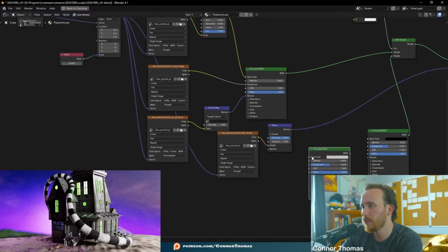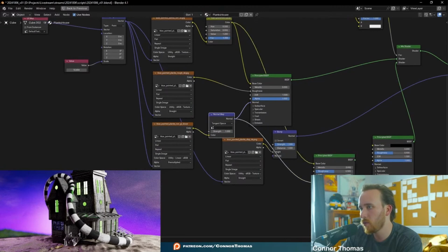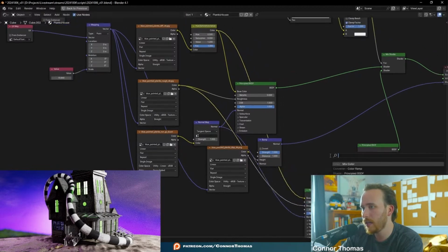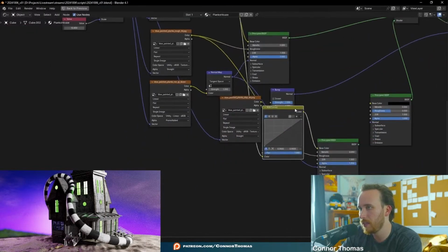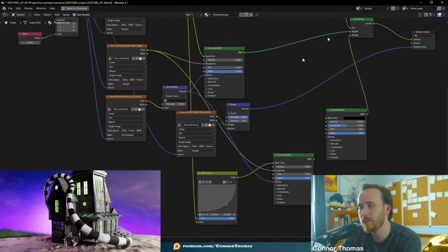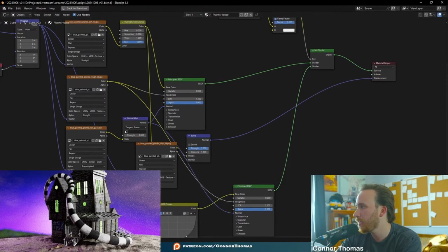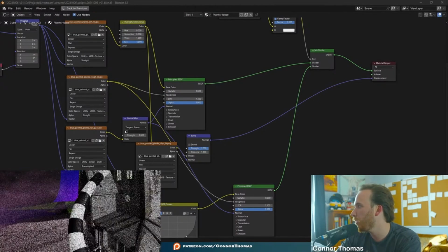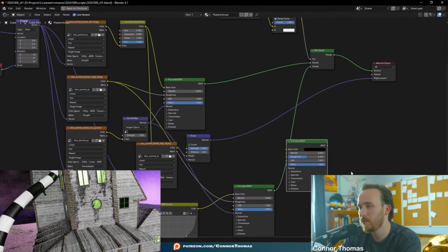So if we duplicate this principled BSDF, we use the exact same base color that it has. We use the exact same normal map that it has. We're already using the same displacement, and then the roughness goes in here as well. All we have to really adjust now is if we do a curves adjustment, like an RGB curves adjustment. I can actually just plug that in here. Put that down there. If we make this pretty dang dark for the color that's going into it, and then we replace the black value of our principled BSDF, now it's just making a darker version of our wood texture. And it's actually using that exact same wood texture that it had before. Whereas, let me show you.